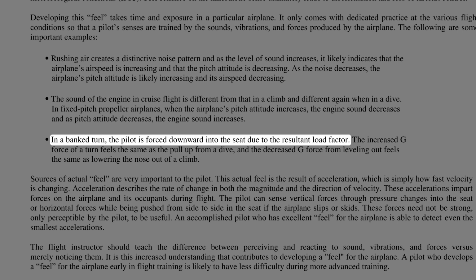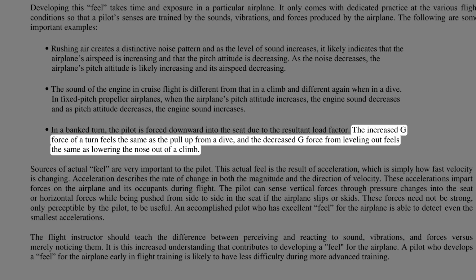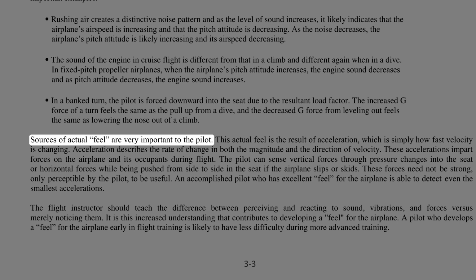In a banked turn, the pilot is forced downward into the seat due to the resultant load factor. The increased g-force of a turn feels the same as the pull-up from a dive, and the decreased g-force from leveling out feels the same as lowering the nose out of a climb. Sources of actual feel are very important to the pilot.